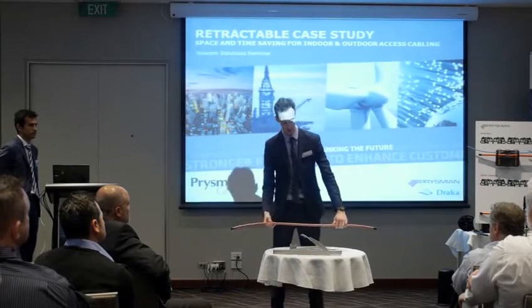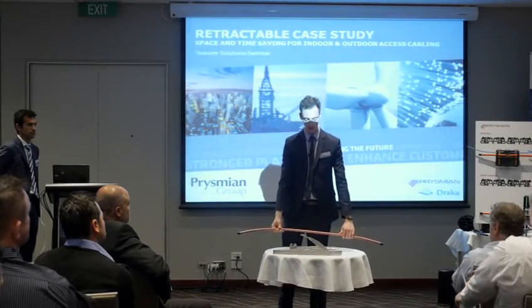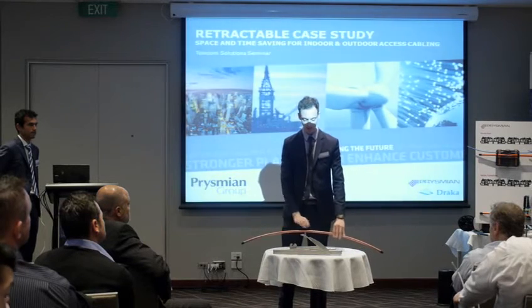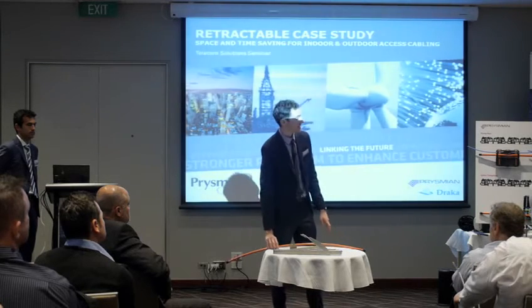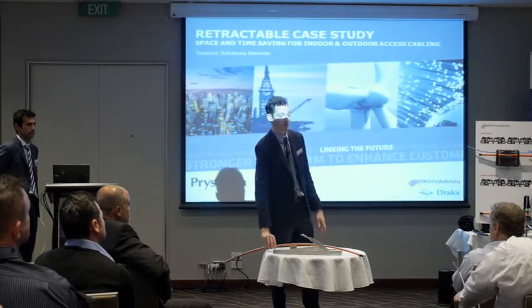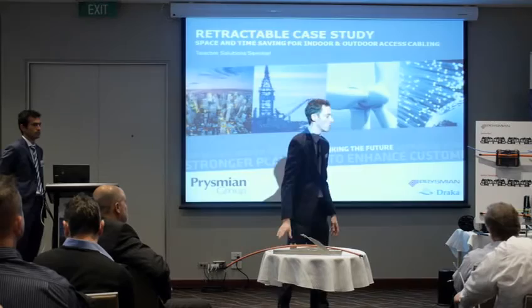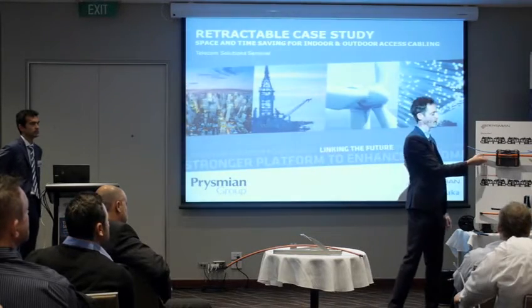You'll notice that there's a stripe on the cable. That's to designate the position of the strength members that are embedded within the sheath at either side. And so when you make your window cut, you make sure not to cut through those. You position those blue stripes on either side, just leaving the orange face visible for the cut. So as I say, the modules are free and loose, as you've seen probably through the samples. There's no water blocking materials within the cable itself.